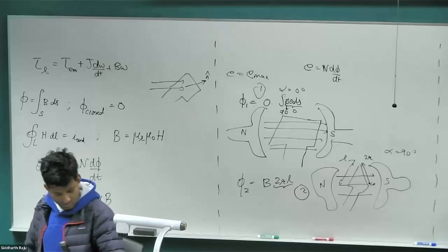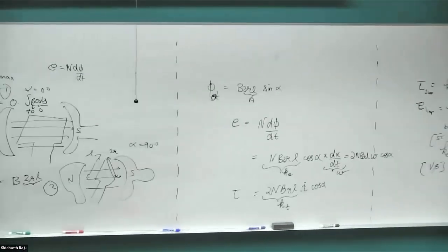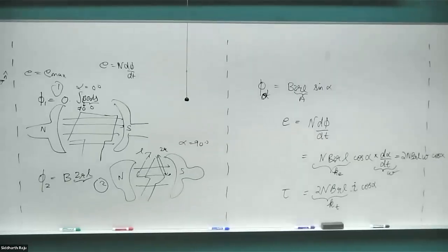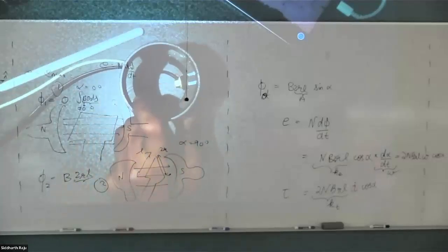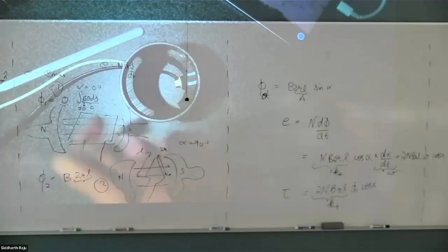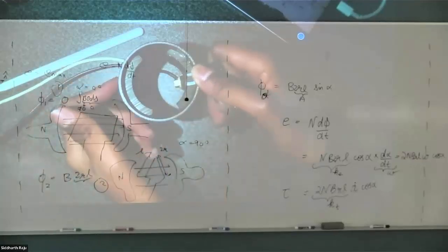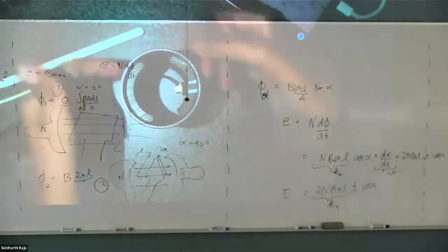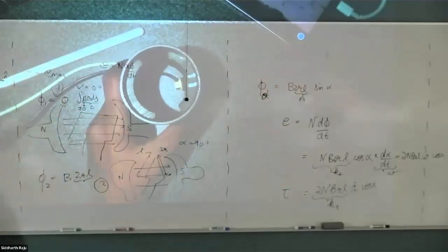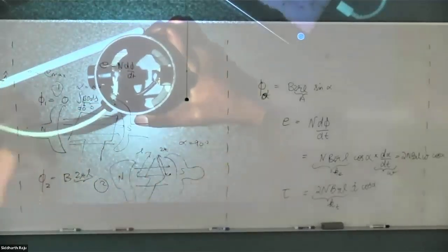Okay, so let's go back to our field lines. This was the two magnets that I drew. The one on the left is, let's say, North Pole, the one on the right is South Pole. The face side is what I marked as North and South, so the back side would be South where the face is North, and North where the face is South, and then the field lines close through the shell of the motor itself. And then our external wires come into